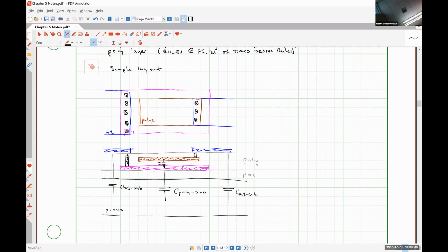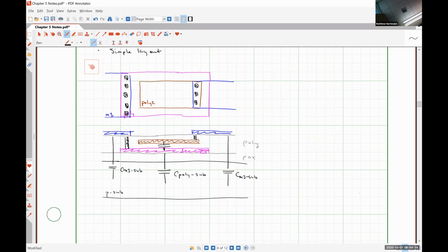So developing a single capacitor on purpose, the one between the poly 2 layer and the poly 1 layer, has generated 3 additional parasitic capacitances, but we can observe that the distance between the conducting plates in each of these cases is significantly larger. So while they will have some effect, our dominant intentional capacitor should be considerably larger.